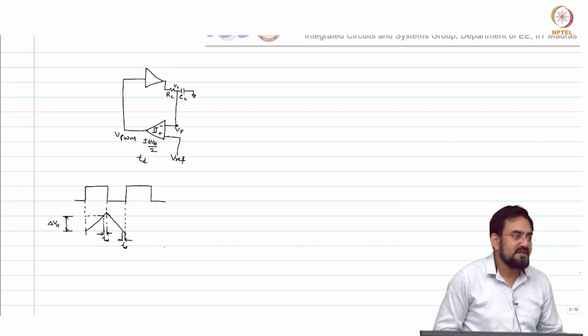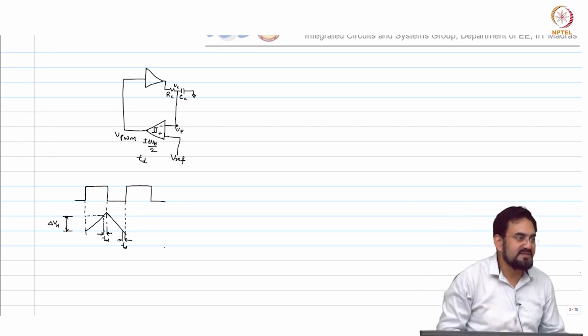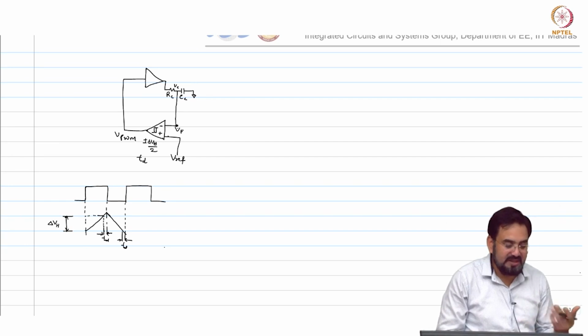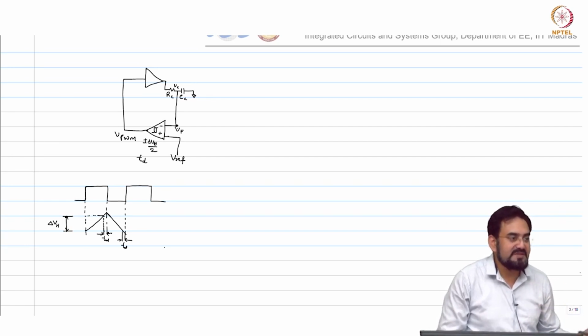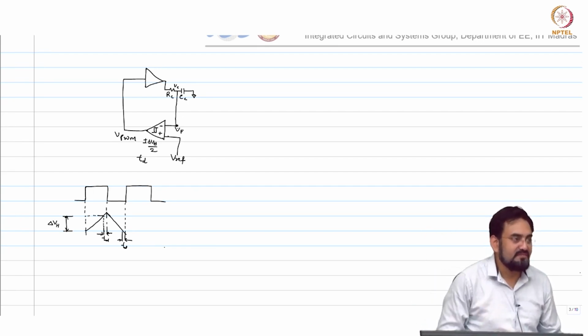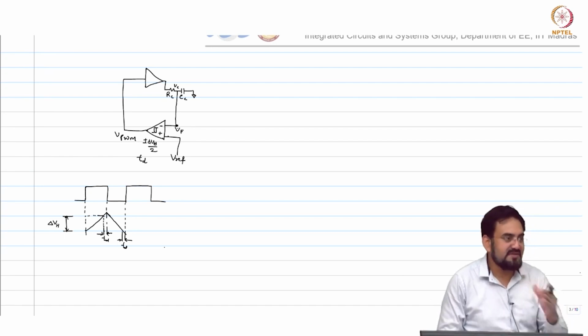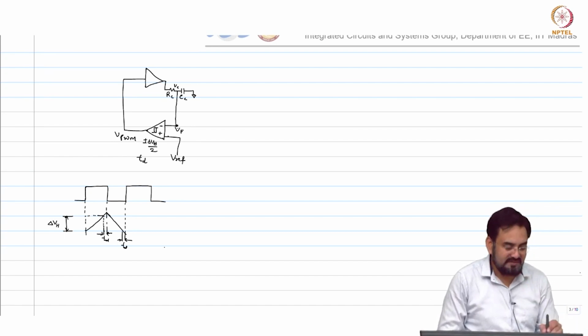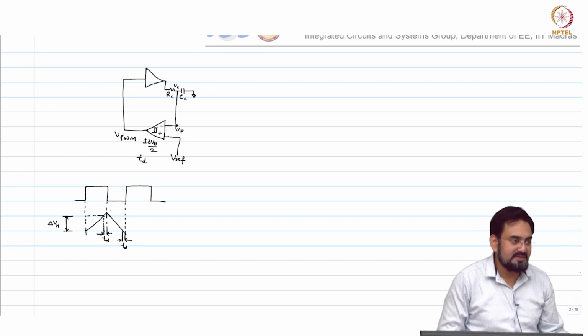If slopes are same, then this delta VH on the higher side and lower side will remain same. So, average will not change, but the slope can be same only if you have 50% duty cycle. If it is a non 50% duty cycle, then one side will be more than the other side, okay, which means at lower duty cycle your rise time is faster, it will be rising faster. In that case, what would happen here? It will peak more and valley will be less.